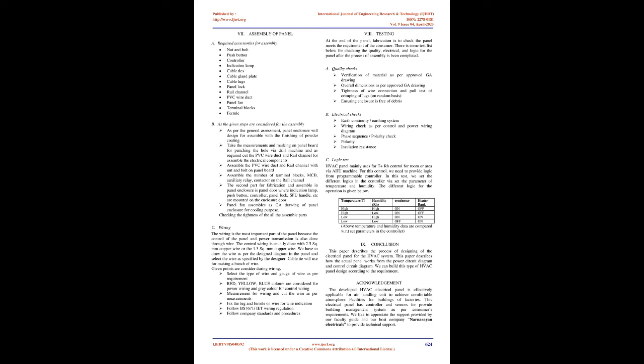There are 2 relays available for auxiliary contact. Power is given to the common contact of both relays. Both relays have 1 NO and 1 NC contact. The AHU fan trip indicator will connect through the NO terminal of relay 1, while the DOL starter with auxiliary relay will connect through the NC contact of relay 1. The DOL starter for the AHU fan motor works with the help of the auxiliary relay, and smooth starting is through the VFD. Moreover, in fault condition the trip signal will terminate by the coordination of the VFD's relay.